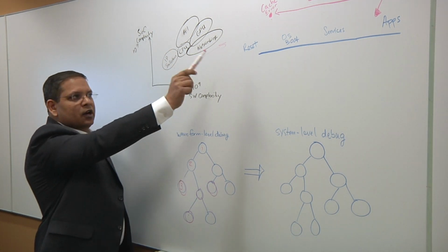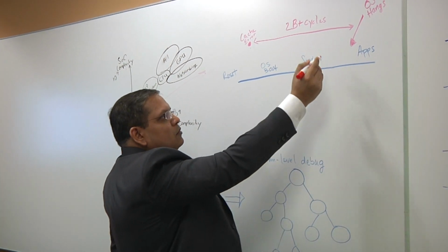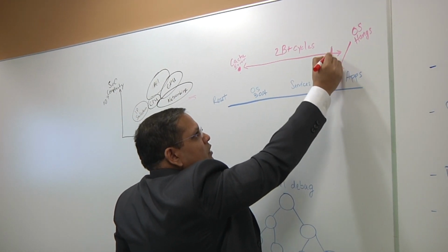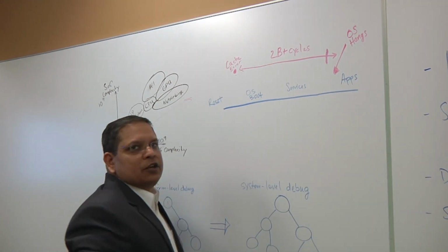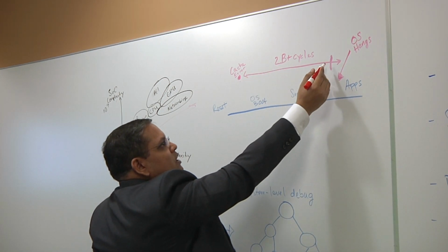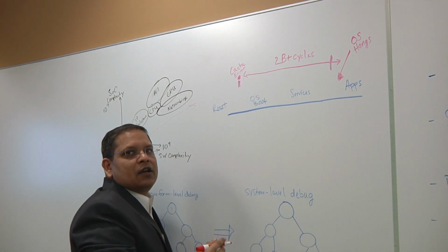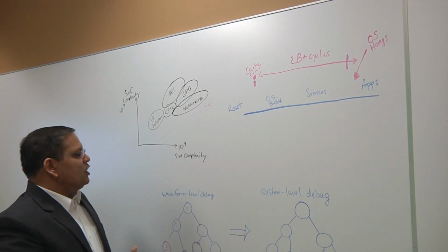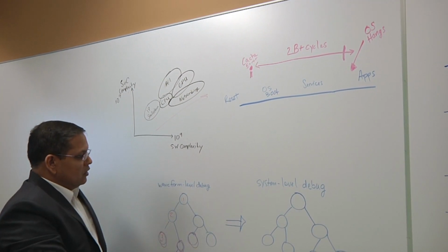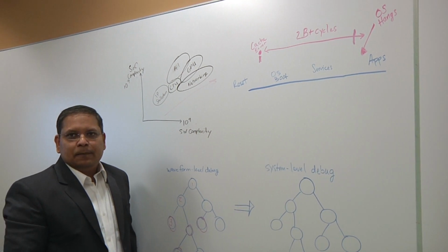Now, if I direct your attention to the problem statement that we drew, let's try to draw to scale. If this is 2 billion cycles, 1 to 2 million cycles is going to be this much window. Now you can imagine how many iterations it is going to take me to get to the window where the cache error is. And hence, the summary of this discussion is that as the complexity is growing, this waveform level debug is not converging fast enough.